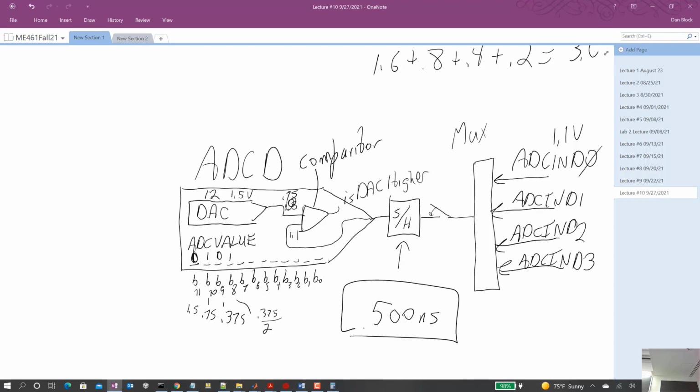So instead, what we're going to do is tell the ADC to convert, and wait for the ADC interrupt. We're going to have an interrupt function be called when the ADC is done, just like our timer interrupts. That makes some sense? Okay.